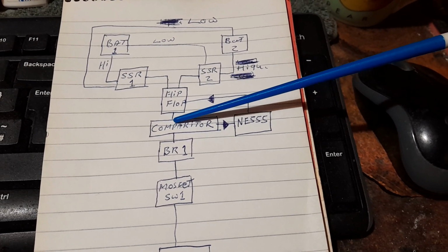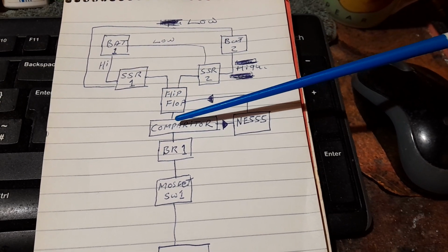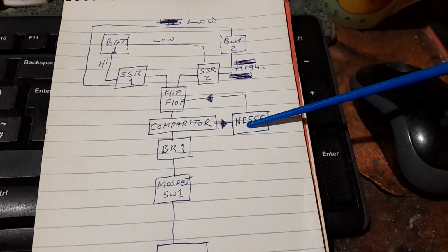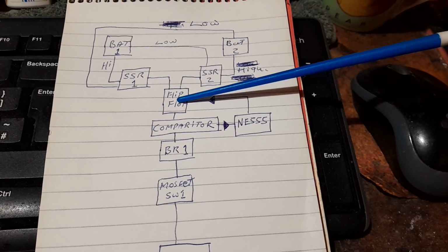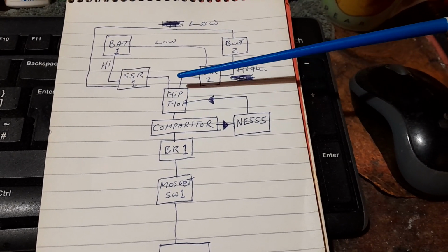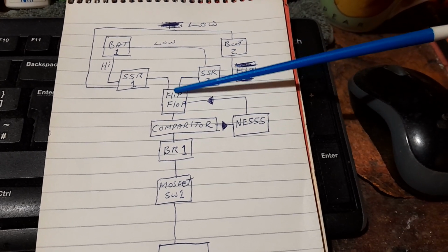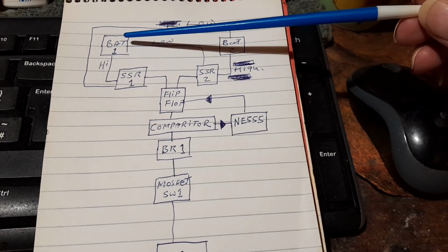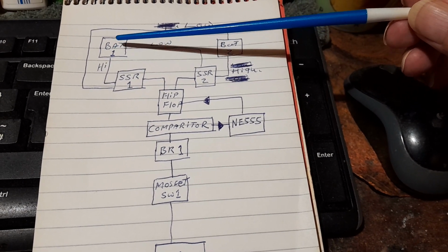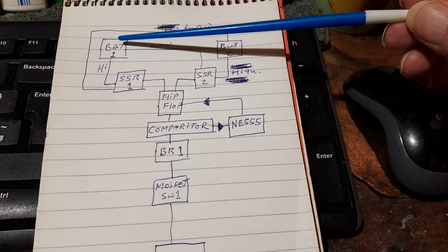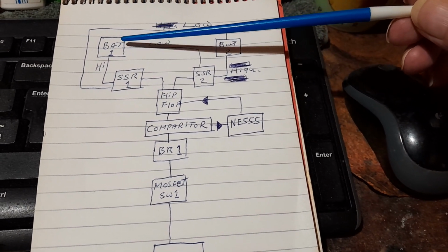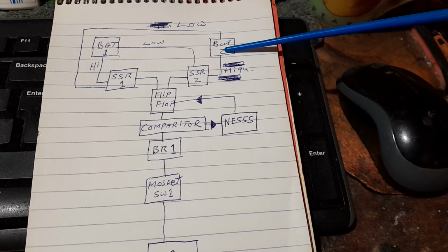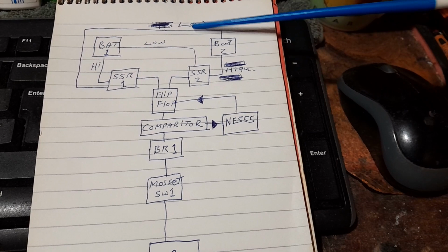When the voltage of the series battery bank drops below a certain threshold point, it will trigger the NE555 timer, which would send a pulse to the flip-flop, which would then activate to reverse the arrangement, so that the battery that was previously low will become high, and the battery that was previously high will become low, right?